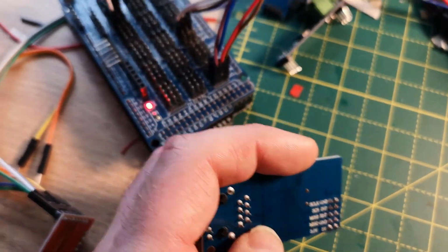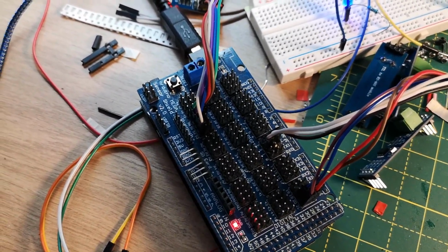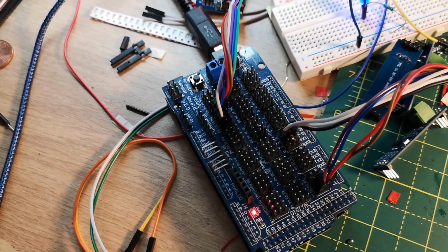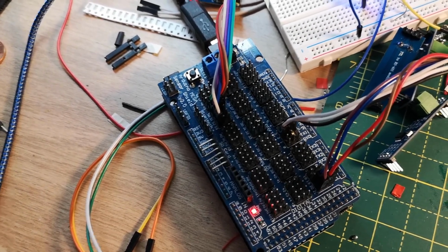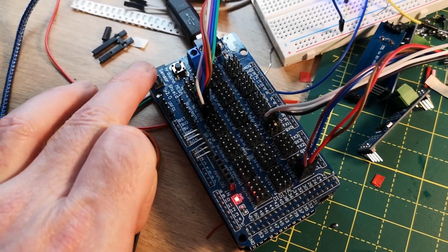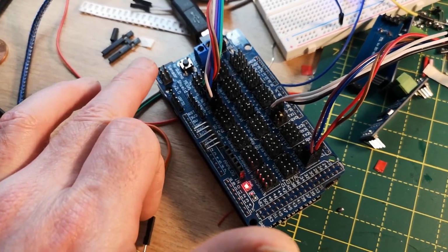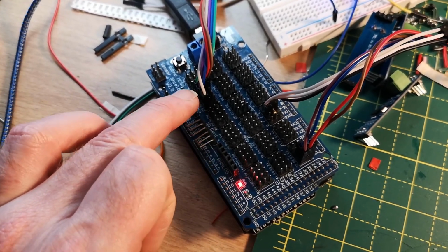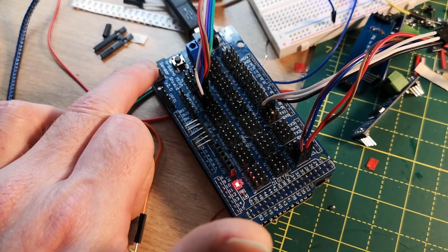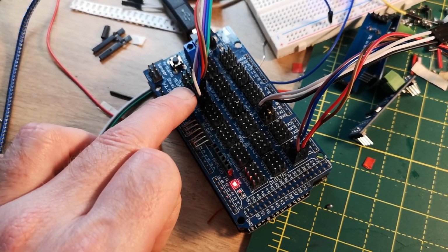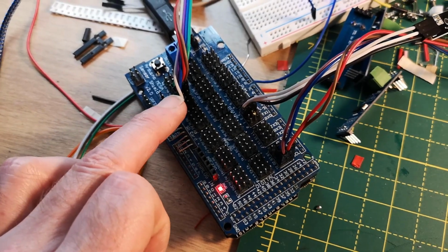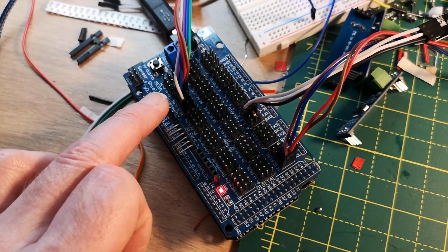The Mega has, on the sensor shield and underneath, an ICSP header, which is over there, but I haven't actually found which order the pins are in, and they're not labelled. I maybe found one picture that shows you, so it might be quite convenient to be able to plug the Ethernet module into there, and I will have a go. However, these pins are also mapped to pins down here, the 50, 51 and 52, I think. So even if I was to use this ICSP header, I wouldn't be able to use pins 50, 51 and 52 anyway. So actually I thought in the end, what better way of reminding myself that I can't use those pins than to plug stuff into those pins.